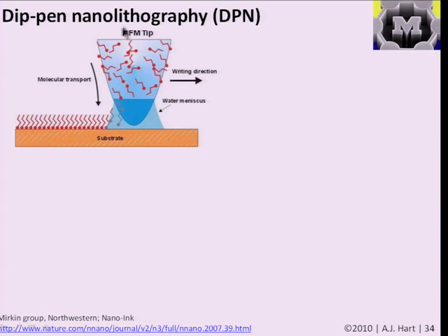upon the existing technology of scanning probe imaging, where AFMs were even back then widely used to take images, and combine it with the idea of a fountain pen, where if you, say, make an ink that contains molecules, you can then use the AFM tip like a writing instrument, and taking advantage of the tendency of the right liquid to flow to the apex of the tip, you could then deposit molecules selectively in desired areas. So you could effectively write nanoscale lines using these tips.